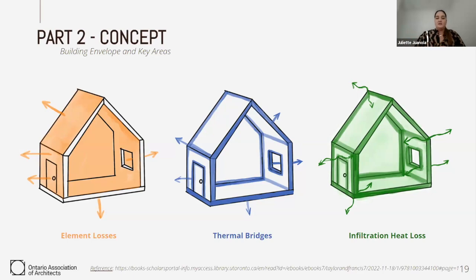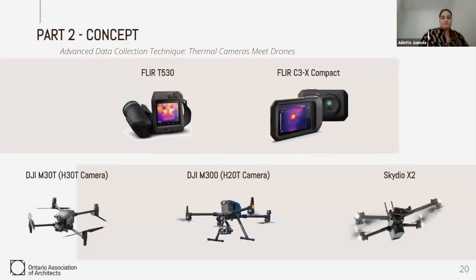So there are many tests that can be performed to make them more visible and increase the contrast when performing a thermography detection on a building envelope. For example, some companies will perform blower door tests in order to increase the pressure inside buildings to kind of force the air to go out of the building envelope, and this will increase the contrast and make it more visible on thermal imaging. So there are really different methods that exist that can be really interesting to make this happen.